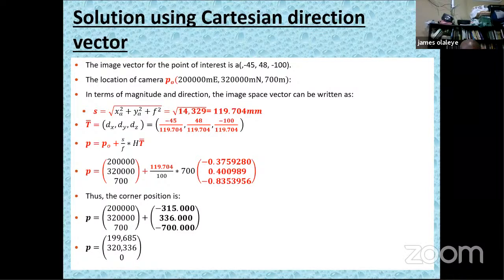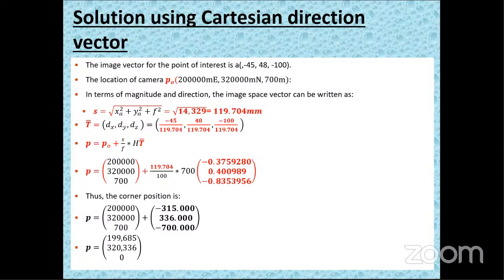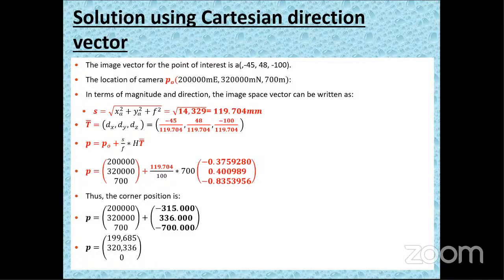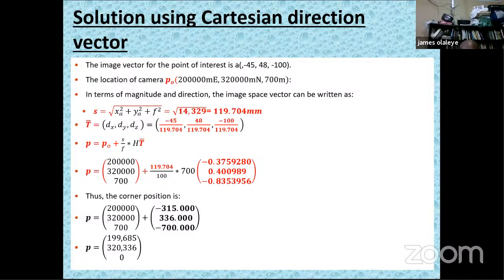I don't know whether there is any special meaning to high resolution apart from either using a high quality camera or flying low. You change the resolution of your image only by flying at different distances. An image that is taken at close range will have very high resolution, higher than one that is taken at longer distances.